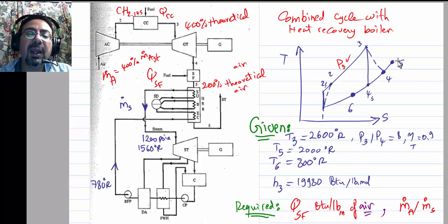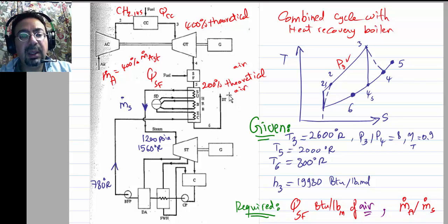Now 5 is hot enough, he sends it at constant pressure into that boiler and it goes all the way to 6. Now at 6, after turning all that water to steam, 6 is cold enough that it's okay to throw it away. So by combining the gas turbine with the steam power plant, you benefit from those hot gases at 4. You don't want to throw them away.